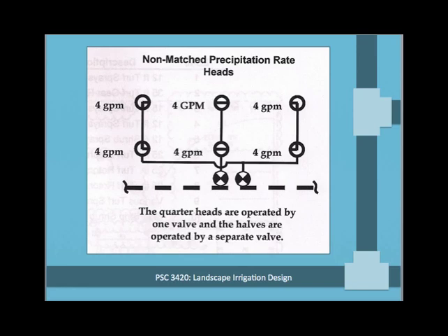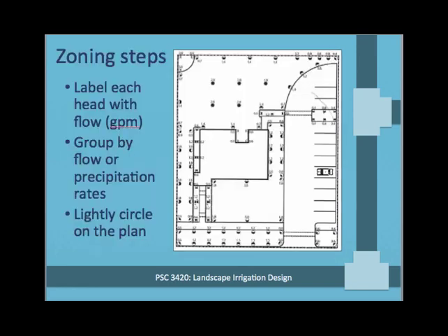It certainly can be done, but you can see that in this case you have to have an additional valve, which you try to avoid for the simple reason that the fewer valves you have, the less expensive it's going to be, the less maintenance and troubleshooting and so on. All right, now back to our example.